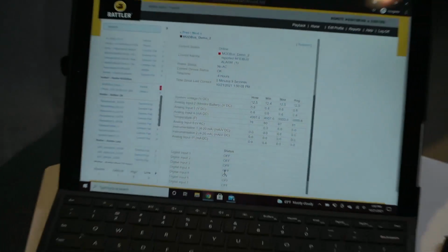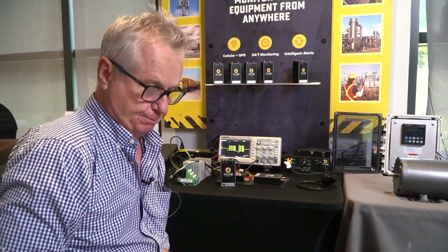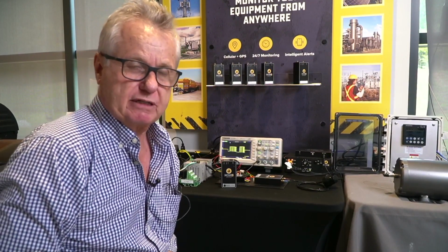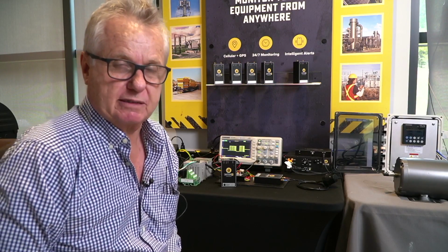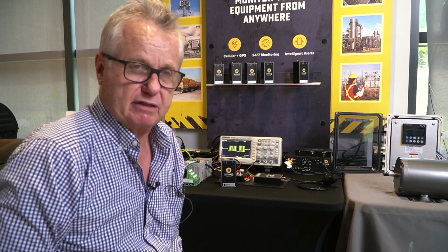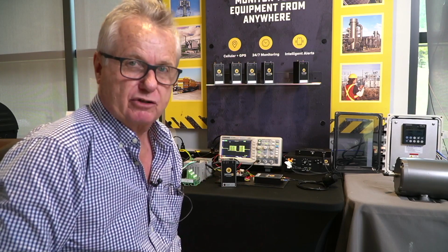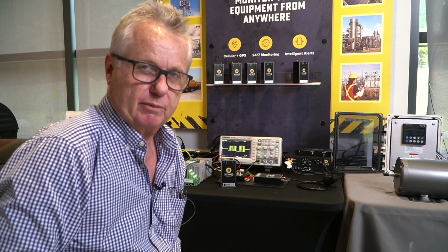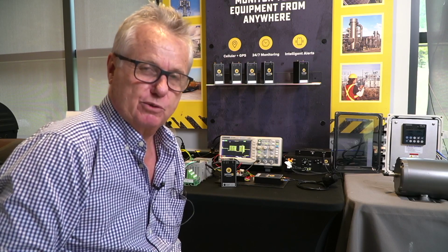That might be connected to a float level, it might be connected to some other kind of status monitoring, a vibration switch, whatever it is, an AC power quality meter, and that can bring back from the PLC, which can be configured as an output or however it's done, through Modbus, and it'll bring this alarm up into Glance, and so you'll always know the health and status of your PLC and all the alarm indications that it produces without connecting the wires, only 2 wires via Modbus.